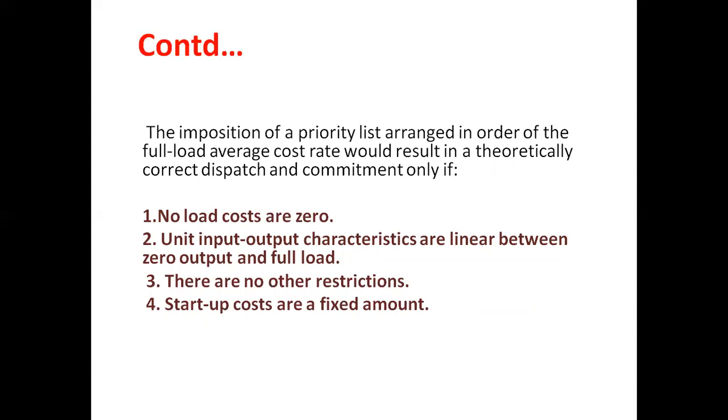which would result in a theoretically correct dispatch and commitment if and only if the no load costs are zero, unit input output characteristics are linear between zero output and full load, there are no other restrictions, and the startup costs are a fixed amount.